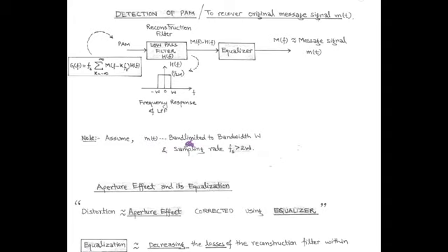So the high frequency components are assumed to be cancelled, and we have only the low frequency component, similar to the message spectrum M(f). The output of the low pass filter is the product of M(f) and the frequency response H(f). It is equivalent to the situation when a message signal is again passed through another low pass filter of transfer function H(f).